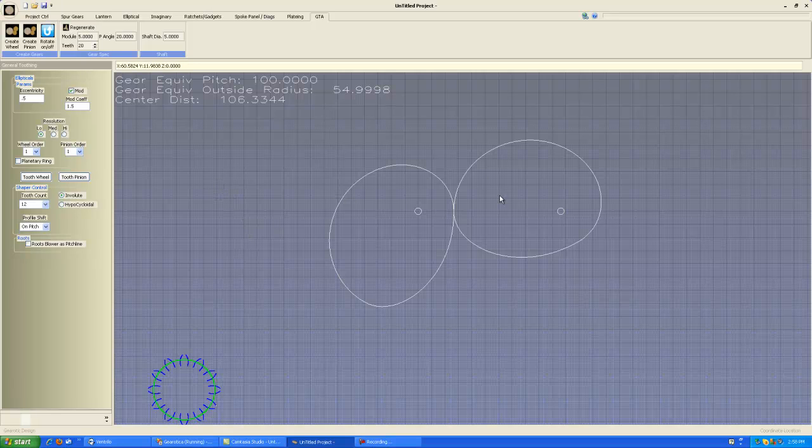There are two ways to tooth shapes in the new module. You can tooth them on an involute shaper, and you can see a picture of the shaper down here at the bottom of the screen. Or you can tooth them with a hypocycloidic shaper, and more shapers will be coming. And in terms of DXFs, what I'm going to try to do is allow a person to draw a shaper of their own. That would pretty much allow us to encompass any type of gear which would end up being a legal gear that would run properly.